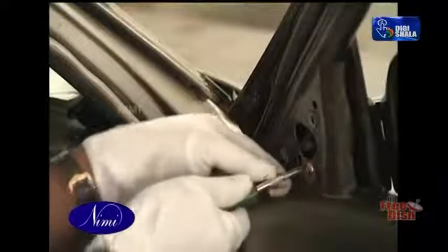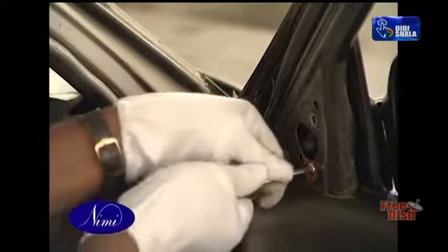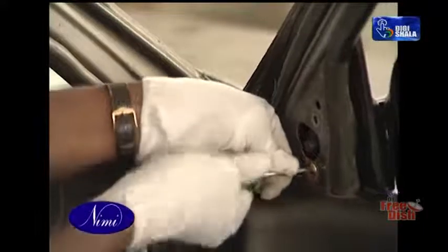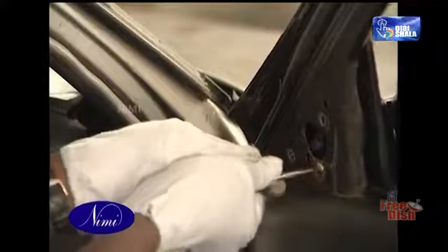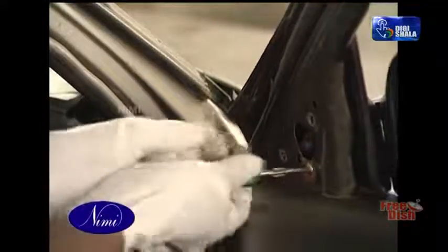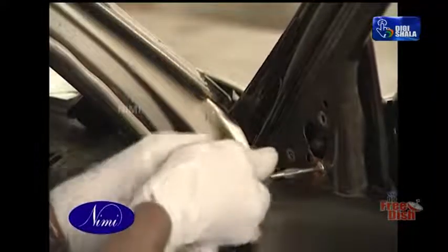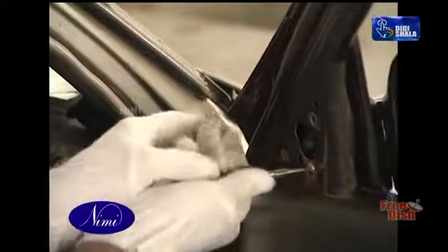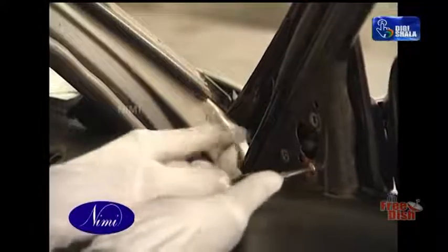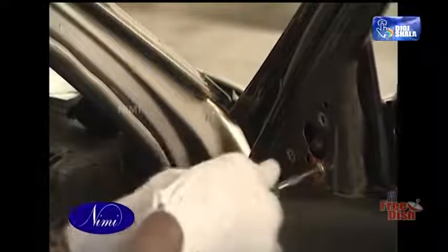Hold the screwdriver with its axis in line with the axis of the screw. Guide the blade with the left hand. Apply a little pressure with the right hand to keep the tip in the slot. Twist firmly and steadily. Keep the tip centered in the slot and the axis of the blade in line with the axis of the screw.